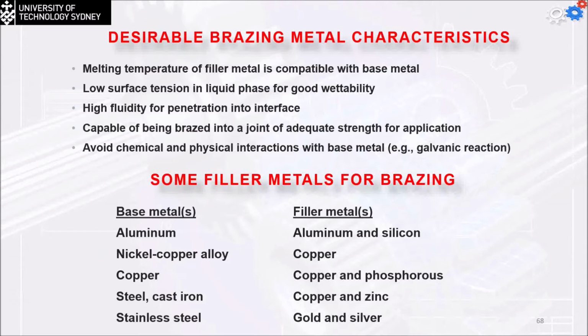Now, have you noticed that most car radiators are made of aluminum rather than copper? The older ones used to be made out of copper. Actually, the heat transfer through copper is better than aluminum. But the material we use for brazing, when we add the phosphorus, is going to reduce the conductivity, and thus make it worse. But in the case of aluminum, we're using aluminum itself, so the whole structure is going to have good heat transfer.